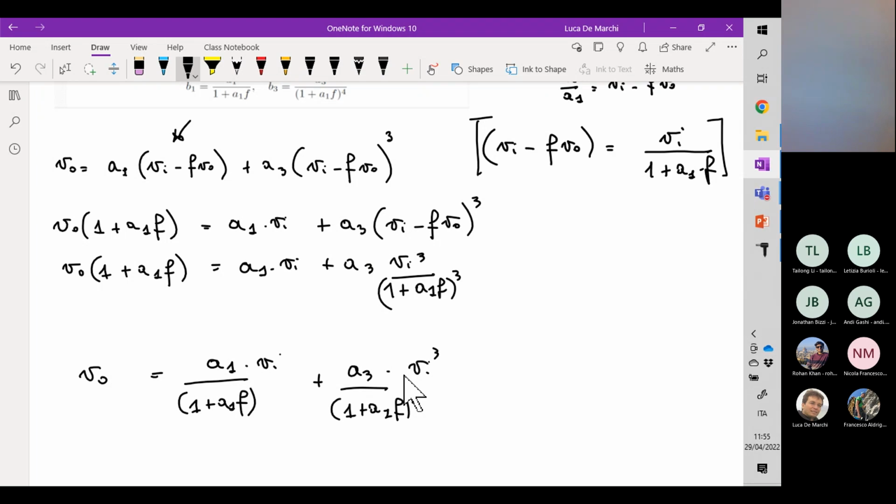So we have discussed the fact that through negative feedback we can achieve a precise gain definition of our circuit, gain desensitization, which means that even if the gain of the amplifying stage changes by a factor, let's say A1 plus delta A, this variation is somehow negligible because of the feedback loop itself.